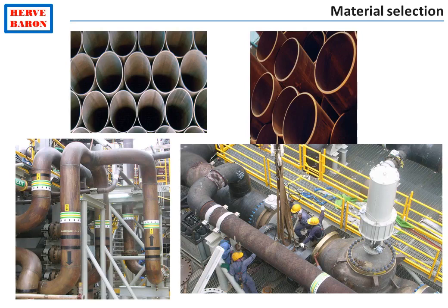The selection of the material of construction depends on the type of fluid handled, its corrosiveness, its pressure, and its temperature. First of all, let's have a look at the pressure. The pressure of the carried fluid will dictate the strength of the material of construction. Naturally, for high pressure, high strength material will be selected to reduce the wall thickness.